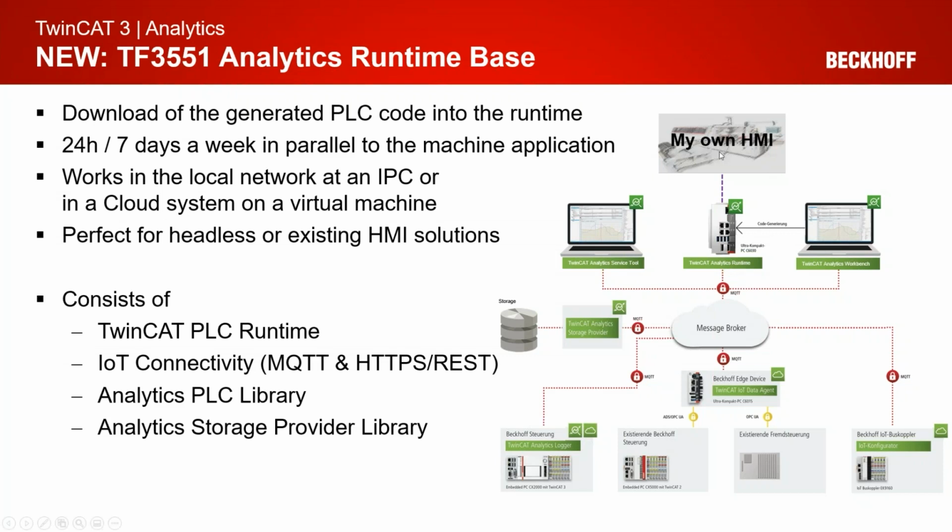If you have your own existing HMI, you can connect to this analytics runtime via ADS or via OPC UA, for example, and integrate this in your own dashboards. And of course, you do not have to pay for something you are not using, and therefore there is this analytics runtime base.